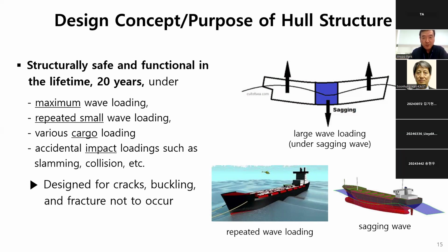The design concept of hull structure is that the hull should be structurally safe and functional in lifetime of 20 years under maximum wave loading, looks like this big wave, and also repeated small wave loading.